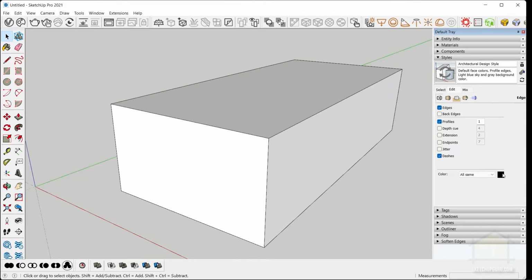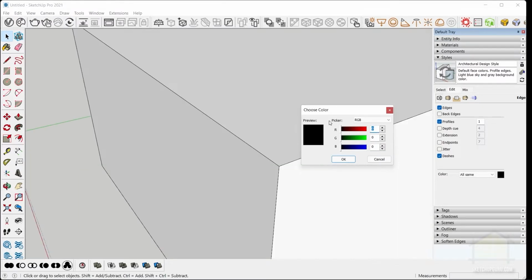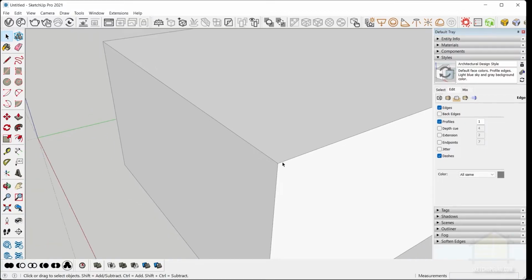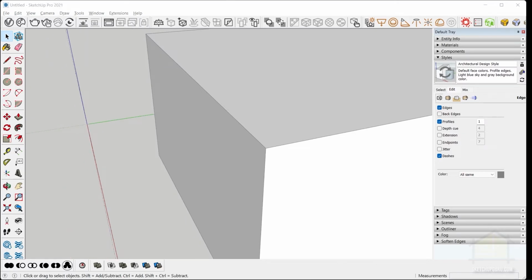And we're also going to change the line color, because when we draw on layout, we would like to highlight certain objects in layout, in the floor plan or in sections. And if this is dark, we won't be able to highlight anything in the plan. So we can change this to a value of say 128 and 128 here. And blue is going to have 128 as well. So press OK. So that would give it a nice dark gray color, which is perfect for drafting and layout for SketchUp as well. So it gives it a pencil look, which is slightly off black, sort of a lead color. And when you want to define something, you can simply trace with black in layout. Or if you want to highlight something, you can trace in black as well.